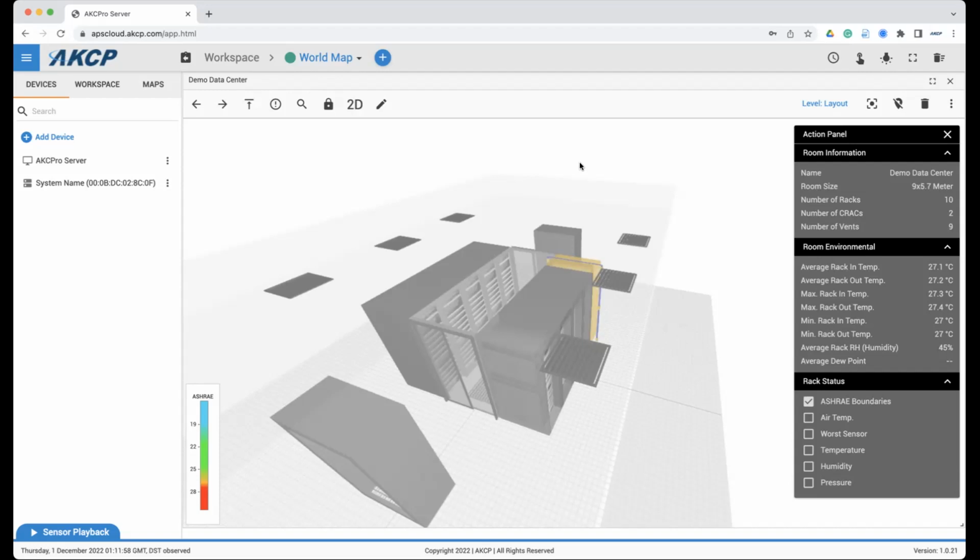And in the transient, you just set the power of the heat that your rack produces, and the rest is computed by the airflow. In your case, the rack bounds the model, so we have to have the information about the air exchange of your rack. So we need either the power or the air velocity, but the probes for the air velocity are more expensive, so you will give the power.